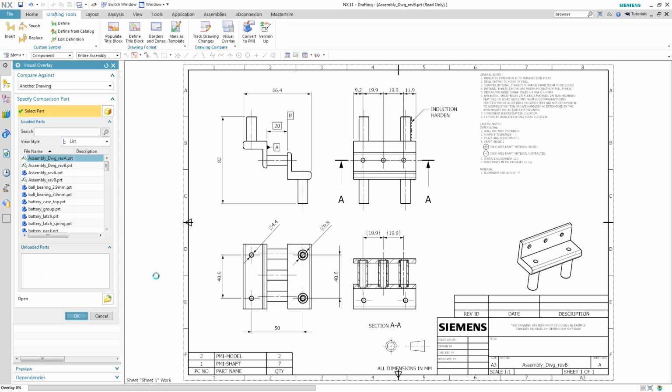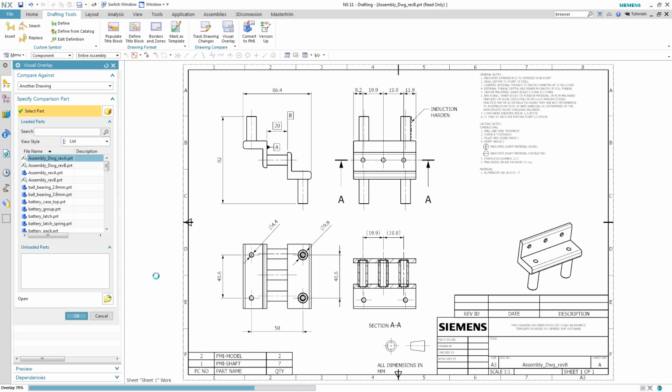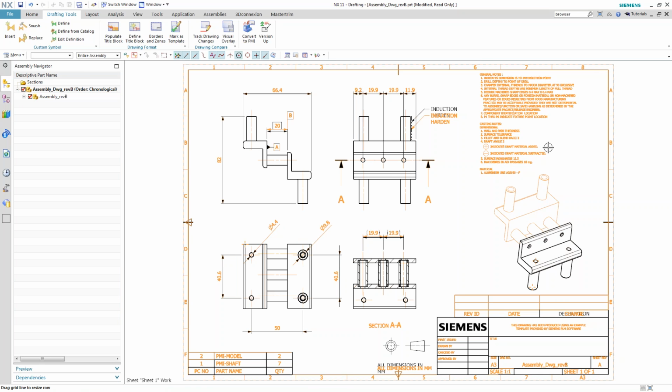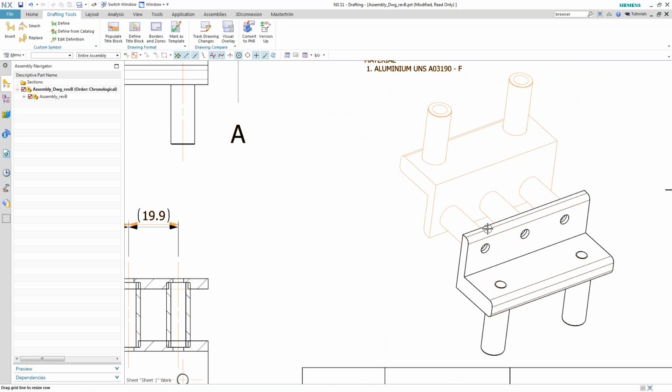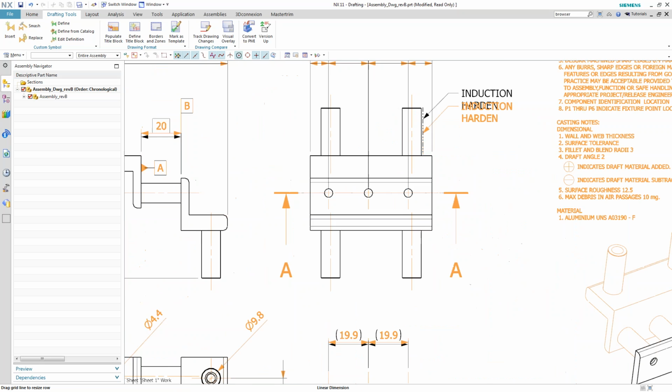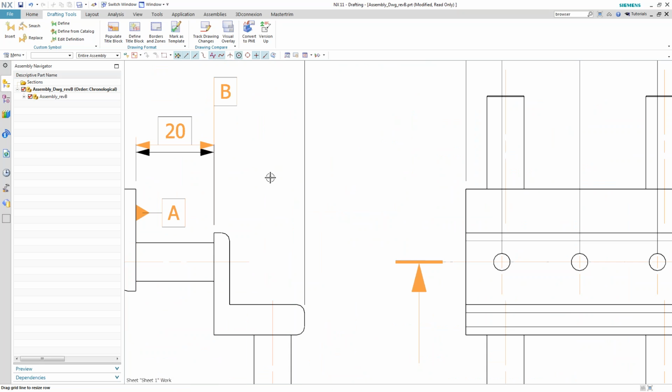And what it's going to do is give us visual feedback of the actual compare. You will notice that it does pick up all the text because it's looking at line elements, and sometimes you'll see that the text is highlighted just because there might be a slight variation. But we can definitely get in and see, like I thought here, I thought something was missing in my drawing, so I can see that this orangish reddish outline here is showing me something that is not on this current drawing. It looks like some of the dimensions may have been moved from previous drawings. That's not that big of a deal.